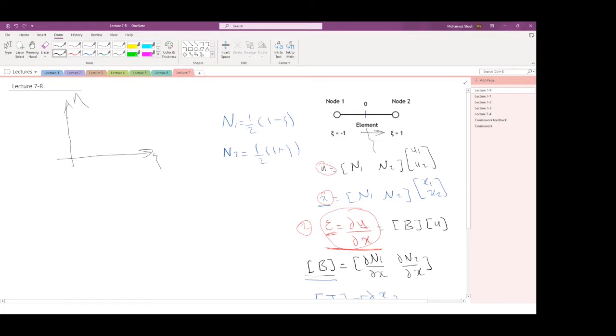The first element we are going to develop is going to be the simplest possible element. So it's going to be a triangle. The triangle will have 3 nodes, node 1, node 2, and node 3. So this is node number 1, this is node number 2, and this is node number 3. The triangle would run between 0 and 1. So the first node is located at 0, 0. The second node is located at 1, 0. And the third node is located at 0, 1. Okay, so I'm going to take this element to a new page and start by deriving the shape functions for this element.